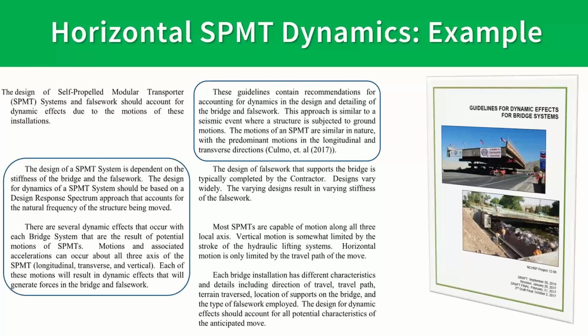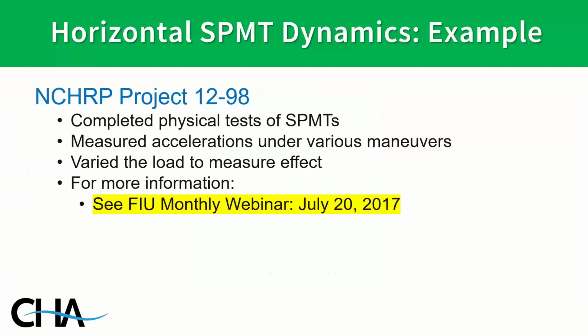There's also bouncing as the SPMTs traverse uneven terrain. We can get vertical accelerations. So we need to account for that in the design of the false work, but also the design of the bridge, because the bridge will experience stresses as this occurs, primarily vertical bouncing.